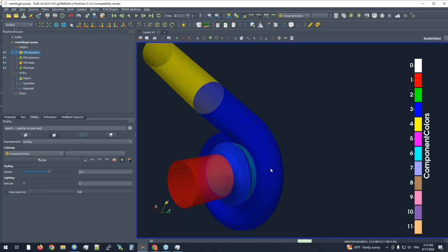Okay. So this also answers the question whether it's close to reality. The results, yes. In general, these turbomachinery applications are very accurate. You practically can't imagine better results. Of course, close to the best efficiency point. The farther you are from the best efficiency point, the more the results could differ from the measurement, for example. But standard cases are very accurate. They're nearly perfect.